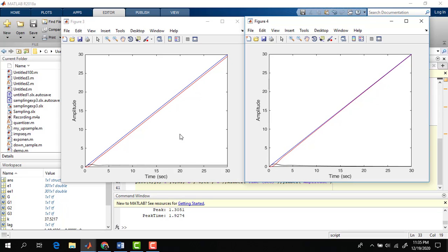One thing to note here is that the function we are using already had a very good response in terms of steady state performance. So the results that we have achieved weren't that visible because the error was already pretty small, but in some cases the error is very high. In those cases you will get better results when you use a lag compensator. So the main purpose of a lag compensator is improving the steady state response. So that's all for the lag compensator. I will come back with another video on the lead compensator.